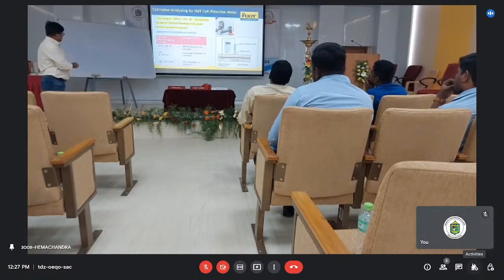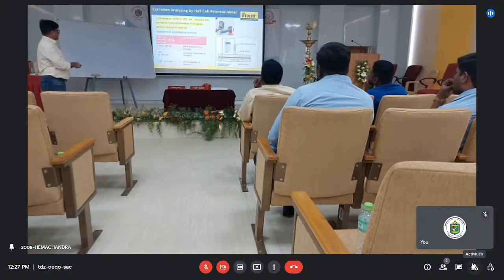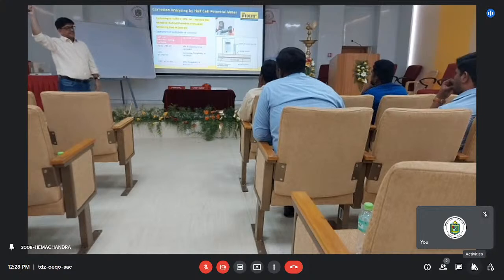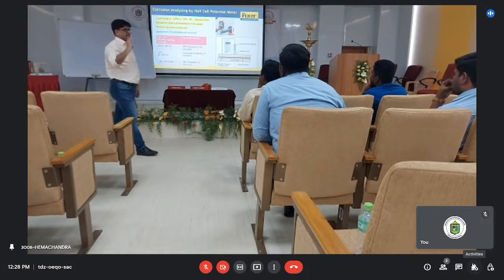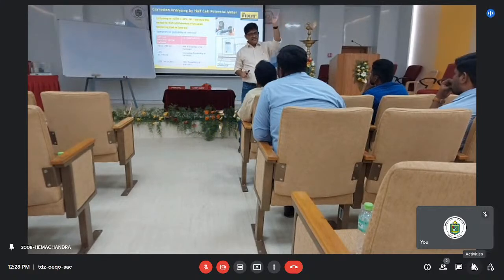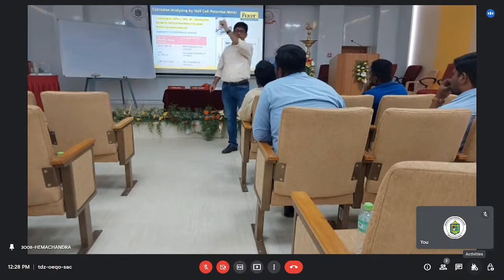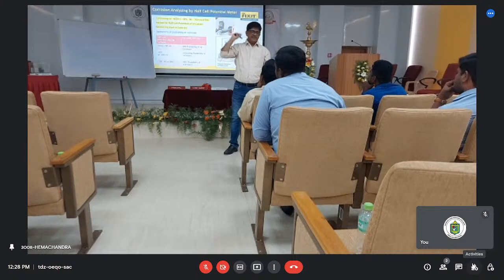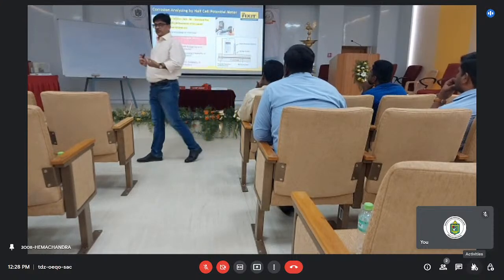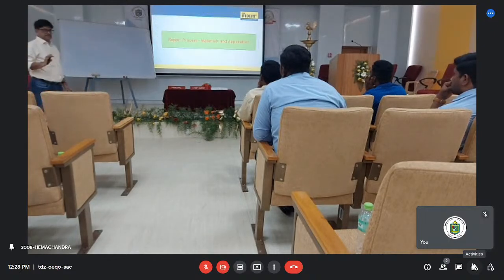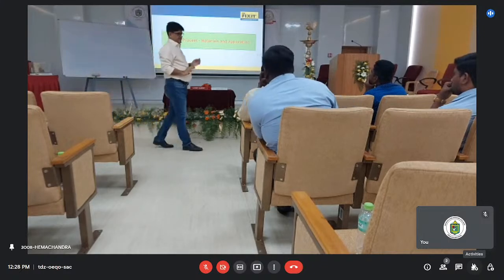So this indication will give you the probability of the corrosion. If your half-cell potentiometer reading is minus 50, minus 200 maybe, then it will be 90% probability of no corrosion. So maybe at this end, you will not get any corrosion. It has not reached up to that. That's why yesterday we showed you Mehta's model, the initiation period. The initiation period has started. It has not propagated up to this point. But if I do not take care of this right now, tomorrow it will propagate. That initiation period we have to take care of. So this is all the condition assessment.